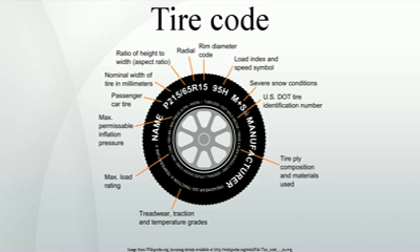In some parts of the European Union, tires that are not fit for a car's or motorcycle's particular maximum speed are illegal to mount. The sole exception are M+S tires, where a warning sticker stating the allowed maximum speed must be placed within clear sight of the driver inside the vehicle. Some manufacturers will install a speed governor if a vehicle is ordered with tires rated below the vehicle's maximum speed.